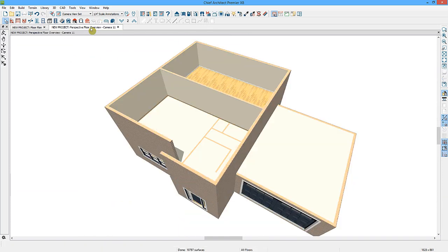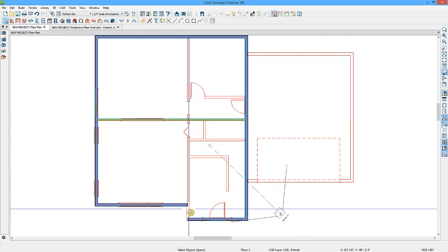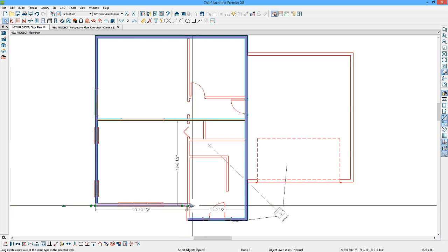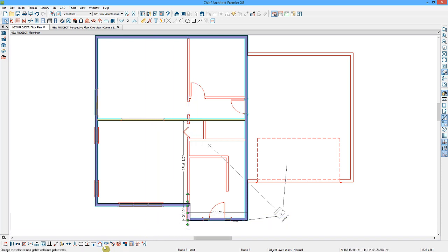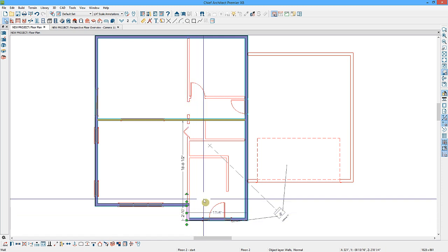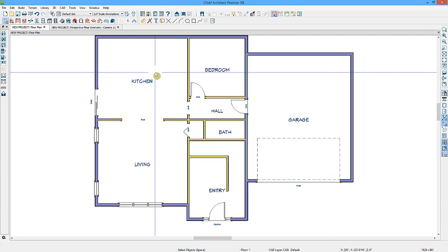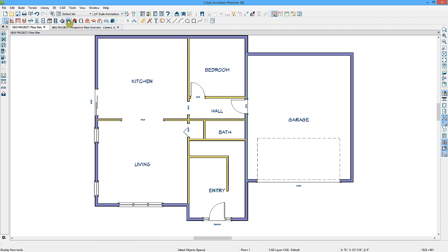If I go back to that floor overview, you can see now that I don't have a floor platform in this area. That's because the walls are not enclosed and can't define the room. So in the floor plan view, I'll simply select this wall and use my same wall type edit handle, the diamond here at the end, click and drag straight down. And you'll notice that my Align with Wall Below tool has appeared. So I want to click on it to make sure that that's aligned with the wall below it. I'll go ahead and turn off my reference display, and then we can go down to the first floor level, and I want to build a foundation under this building. So we'll go back to the Floor Tools parent tool.